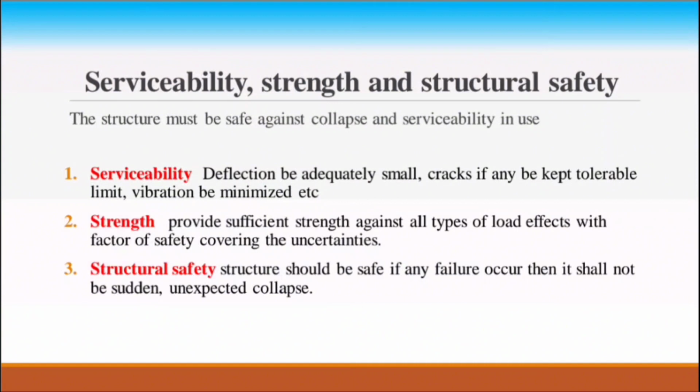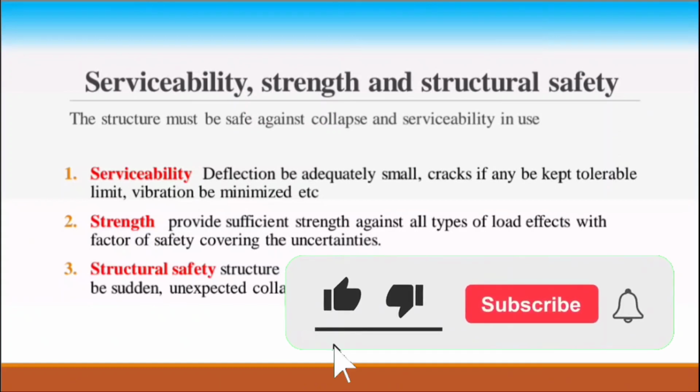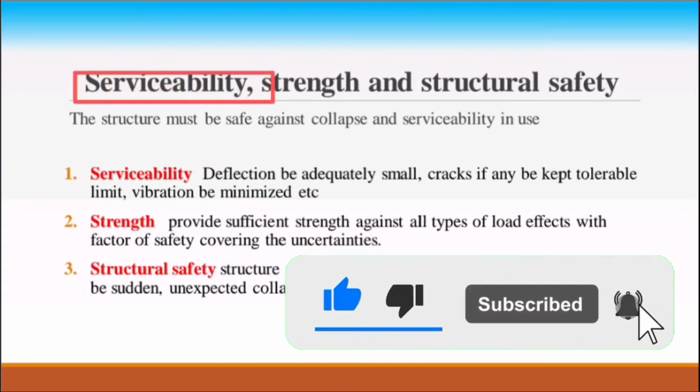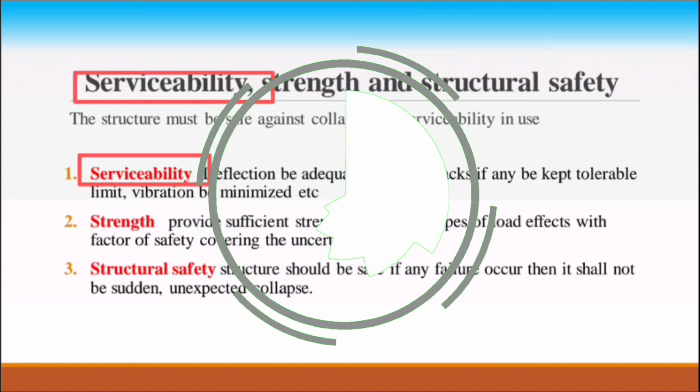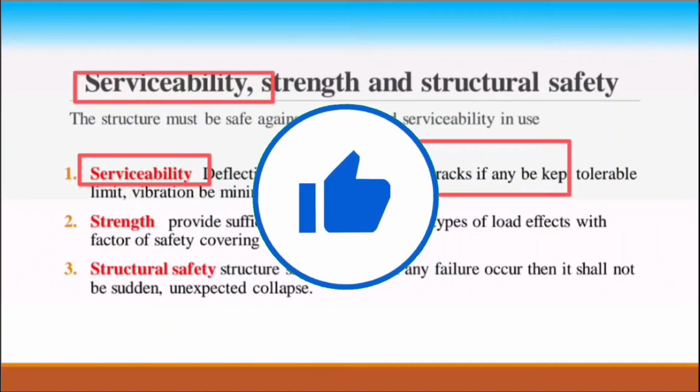For design philosophy, we should understand three terms: serviceability, strength, and structural safety. Serviceability means that the deflection is adequately small, and cracks, if any, are kept within tolerable limits. If cracks occur, they should not cross the tolerable limits. Vibration should be minimized. These terms come under serviceability, meaning the structure should serve the purpose for which it was designed. Remember these terms.